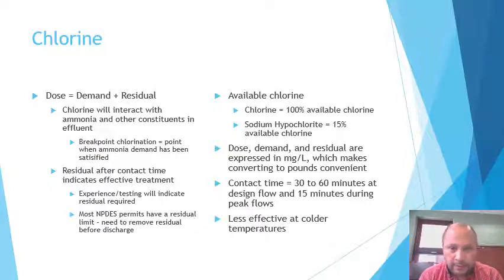And like with most other things here at the plant, the EPA gives you a limit. So we test for E. coli. These are indicator organisms, E. coli or fecal coliform, that are easier to test for than the actual pathogens in the wastewater. And by doing that test, if we meet our limit, we know if we're eliminating those indicator organisms, we're also eliminating the pathogens that are in the wastewater alongside those indicator organisms.